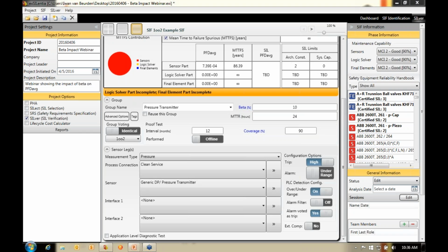It's almost no difference, but there is a slight improvement because the 1oo2 system is behaving more like a non-redundant system, and non-redundant has fewer spurious trips than redundant from a 1oo2 perspective. So that is how this PFDavg works in Exida.